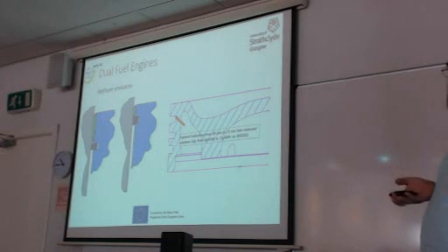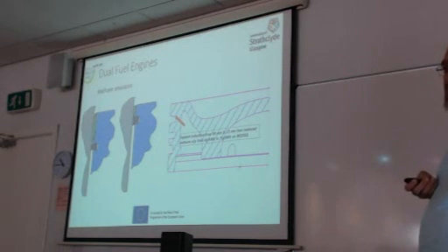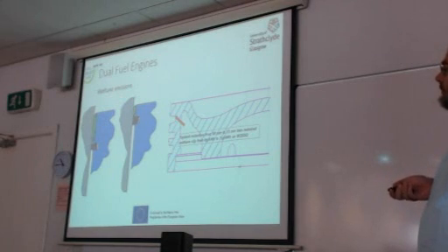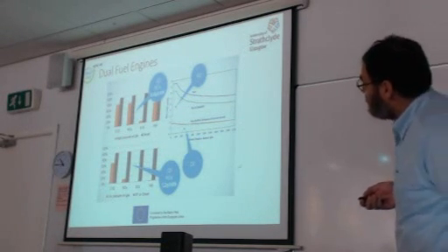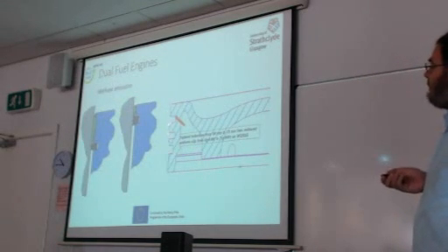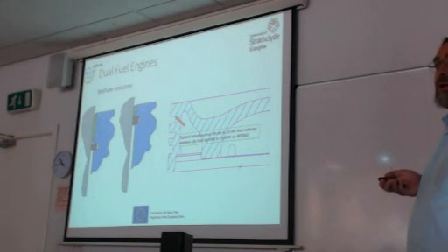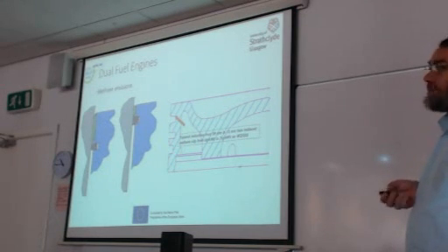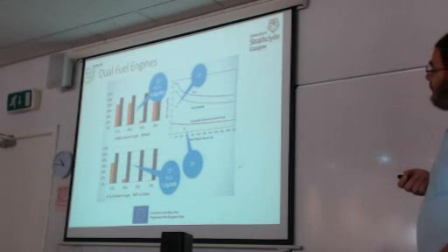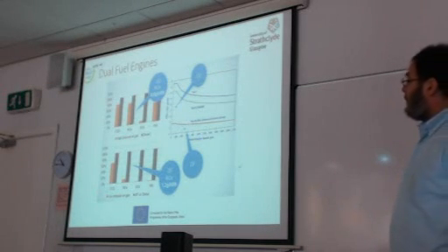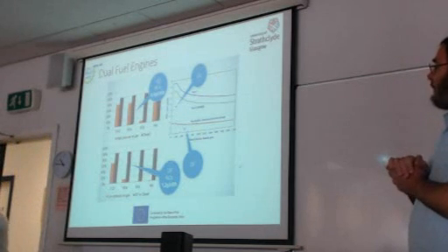And of course, the basic constituent contained here is methane. LNG contains 90% of methane, or close to 90% of methane. That means that the basic problem with burnt hydrocarbons is in terms of methane emissions. I don't have methane emissions here, but I'm not sure if I have some. No, the methane emissions are kept at levels of, let's say, 4 grams per kilowatt hour. So up to now it's quite acceptable, but certainly some changes in the initial design of diesel engines are required.